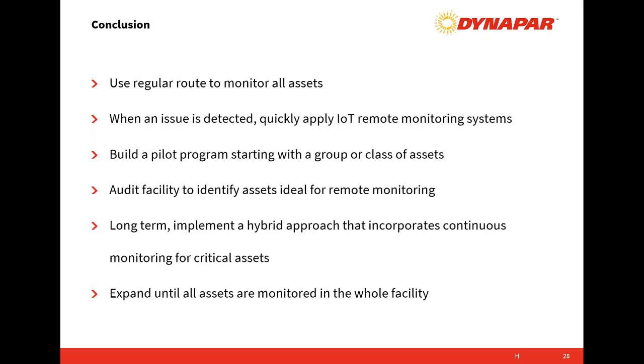Did you get the question about the submersible probe? Sure did. Yeah, IP68 rated, good for submersibility. The stainless steel enclosure, obviously, is kind of the gold standard from a chemical resistance perspective. And then the potting compound that we use, we found, is highly impervious to chemicals. Even the chemicals that are on the do not use list aren't effective in depotting the sensors.